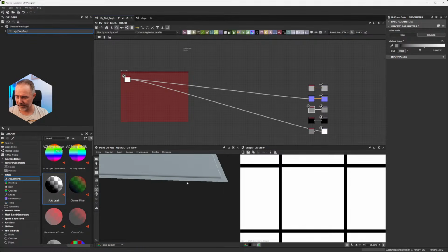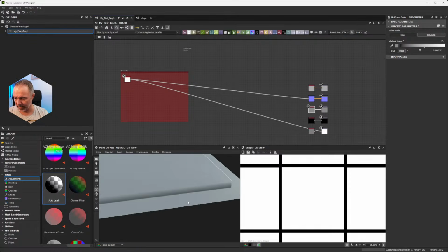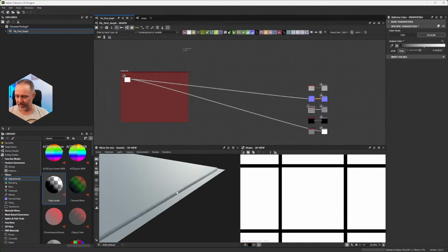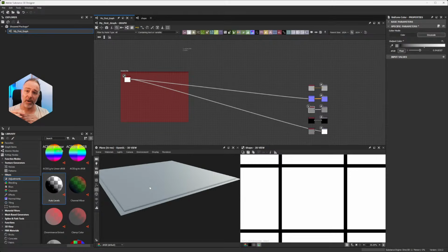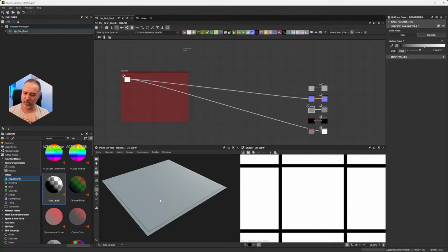Here you see that now we can see the relief. That said, I have black and white, and this is important in the height map to use the maximum amplitude, but you also want this object to reflect the height you want in real life. This square has 100 units on each side, but 100 units doesn't mean anything for you.